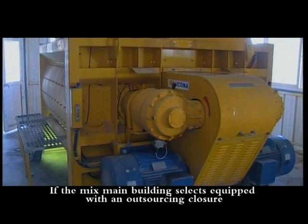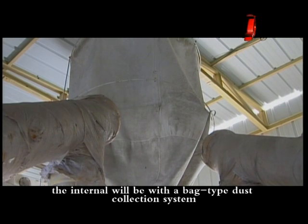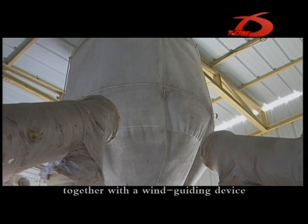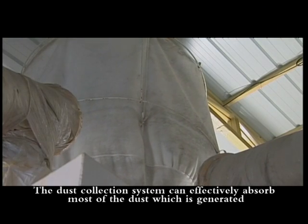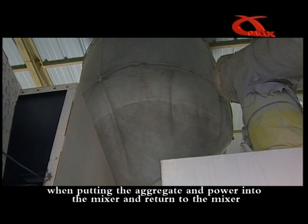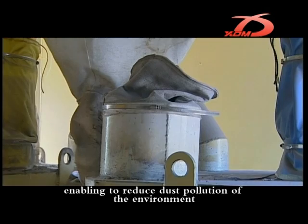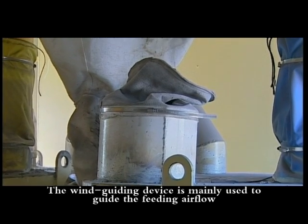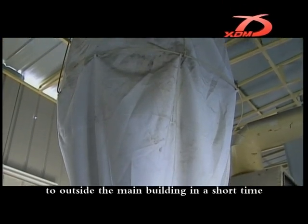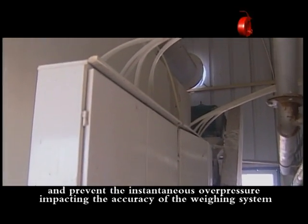If the mix main building is equipped with an outsourcing enclosure, the interior will have a bag-type dust collection system, together with a wind guiding device. The dust collection system can effectively absorb most of the dust generated when putting the aggregate and powder into the mixer and return it to the mixer, reducing dust pollution of the environment. The wind guiding device is mainly used to guide the feeding airflow to outside the main building in a short time and prevent the instantaneous overpressure from impacting the accuracy of the weighing system.